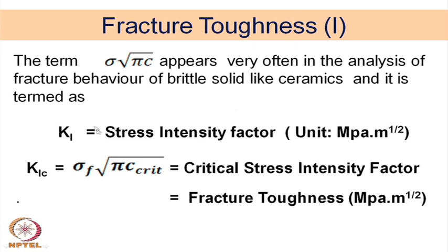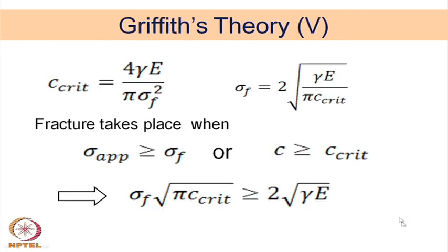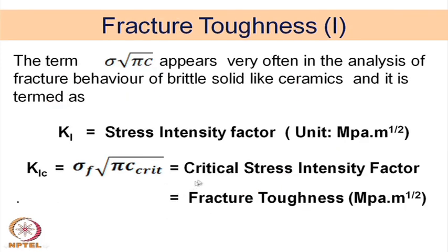Okay. This is the stress intensity factor Ki with the unit of megapascal meter to the power half, and the critical value, when this stress is sigma f, the particular value at which the crack initiates, or the critical length of the crack, that is what we have seen earlier, this particular term, okay, is the critical stress intensity factor.